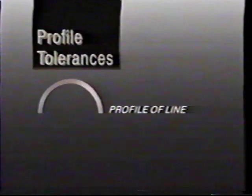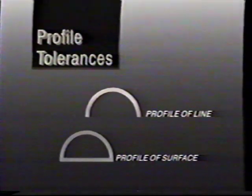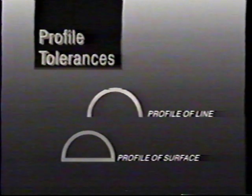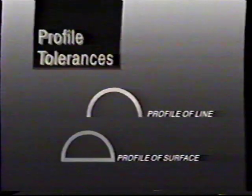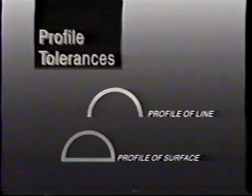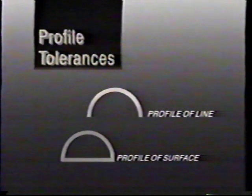The second category of geometric characteristics is profile. A profile is an outline of the feature from either a top, side, or front view. There are 2 types of profile: line and surface. Profile of line tolerances control a single line element. Profile of surface tolerances control all the elements on a part's surface.